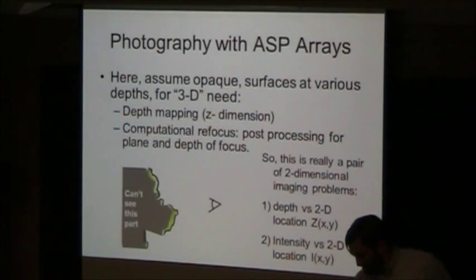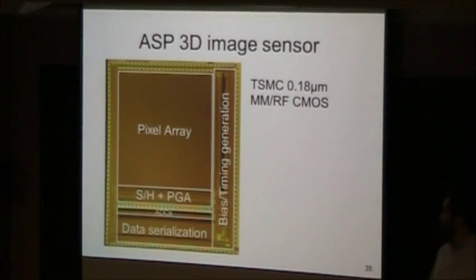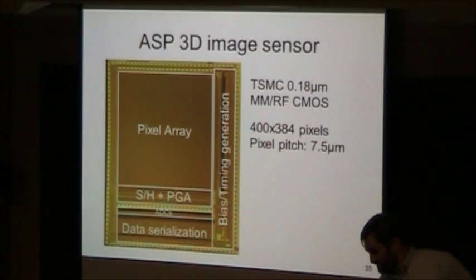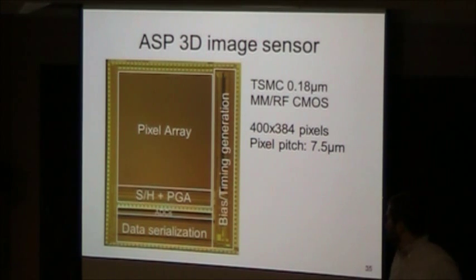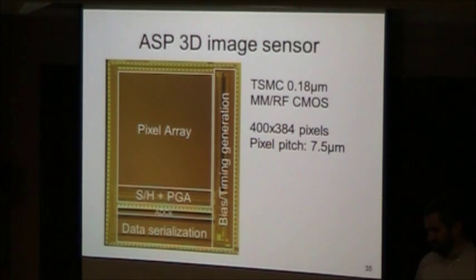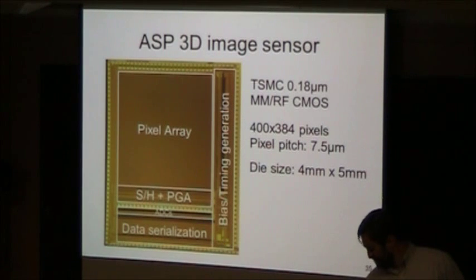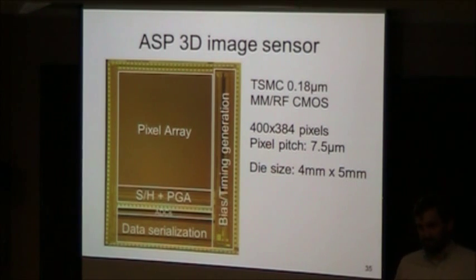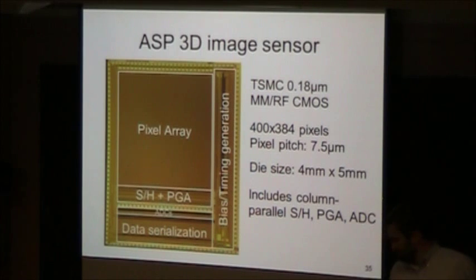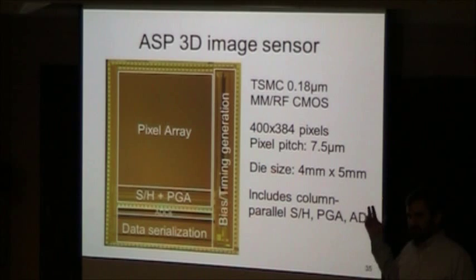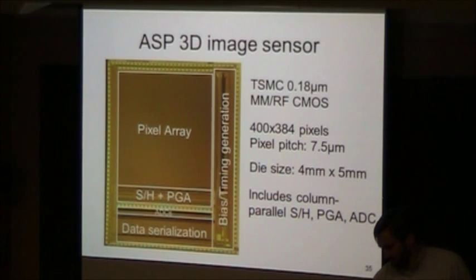In order to make this interesting, we need a bigger chip, so we built one. So this was manufactured in another standard manufacturing process. We designed it on a computer, we shipped it with a check to Taiwan, they shipped us back a bunch of chips. Off we went. Briefly, some random little specs. It's a multi-100 kilopixel camera or sensor. It's about as big as you can buy for reasonable money, and includes not just the optics but also various electronics, so multiplexing and all sorts of things that are easy to do in CMOS.